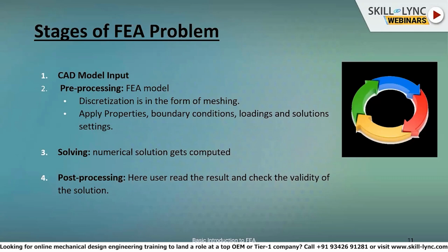There you have to specify the load step, and the step where you define what type of analysis you want to do and what output you are interested in. All that data you will provide there. Then after that we go for the solution, where the software actually runs the program at the back end and tries to solve all those partial differential equations and gives you the result for the entire domain in the form of displacement, stresses, and strain.